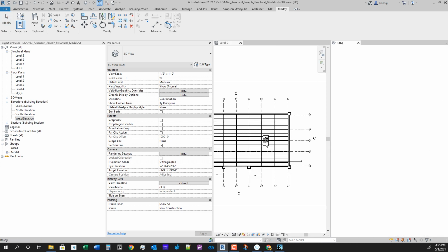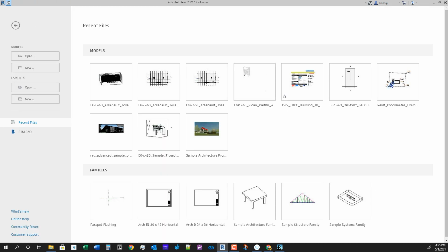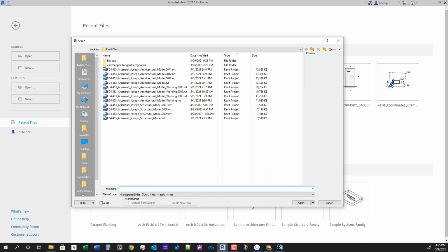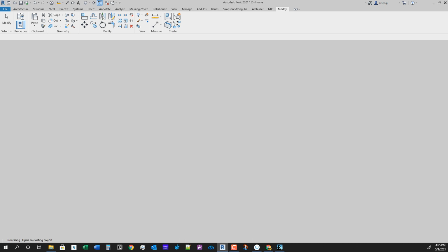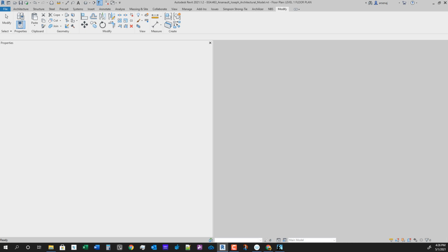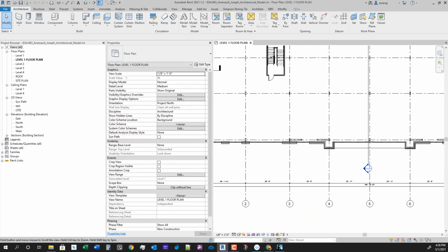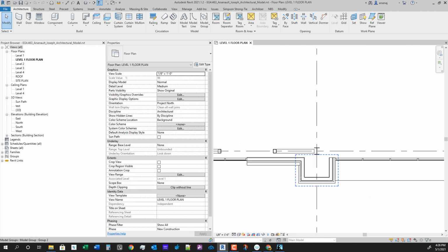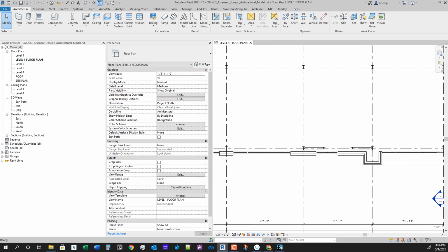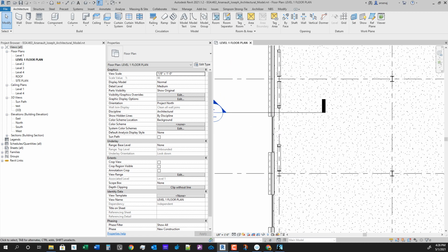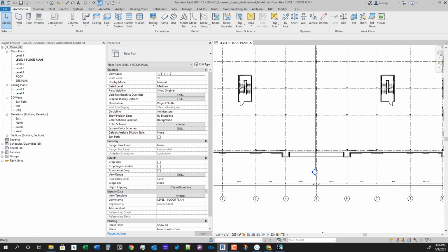Now let's close it, because you can't have a linked Revit model open, so we couldn't open the architectural in the same session. Now, if your computer can handle it, I often will work in 2 different sessions of Revit. So I'll have 2 different sessions open and running of Revit. And that makes it so that you can modify it without having to close the other ones. And so now we should see that it automatically updated these locations. And let's make sure our windows are going to work with how we adjusted our columns.